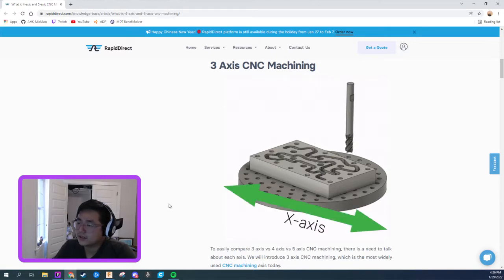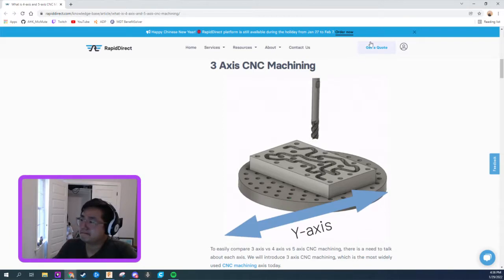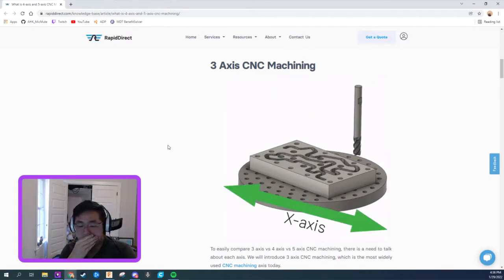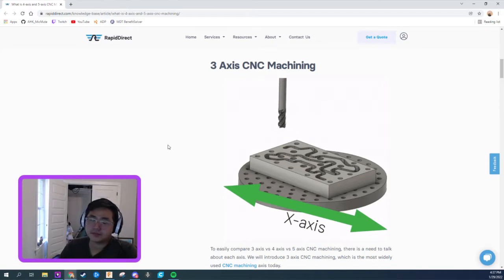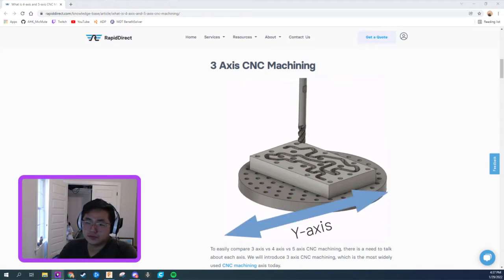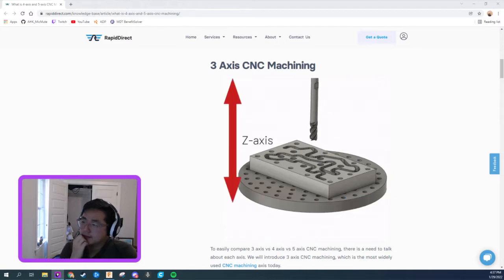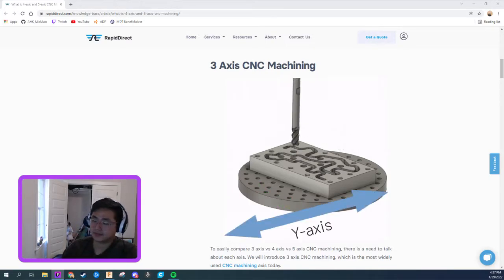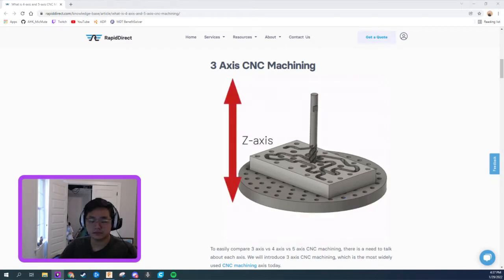Yeah. One thought about knowing the capabilities of the shops that you're working with is that it's good, because then you can tailor your part to those capabilities. In general, as Abel alluded to, the more setups, the more times they have to turn the part, pull it off the machine and put it on, your accuracy goes down between those features, as well as the cost. The cost goes up because more hands have to touch the parts.